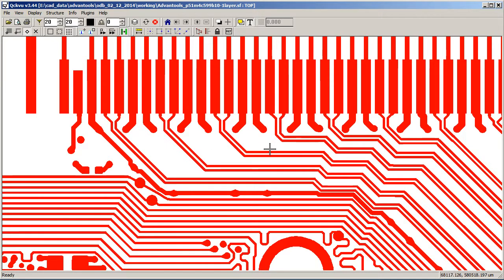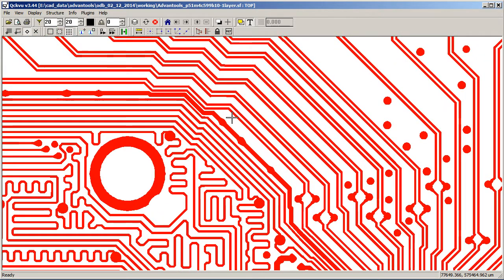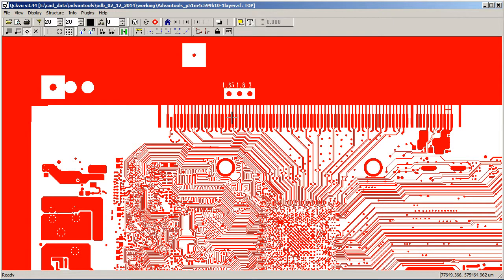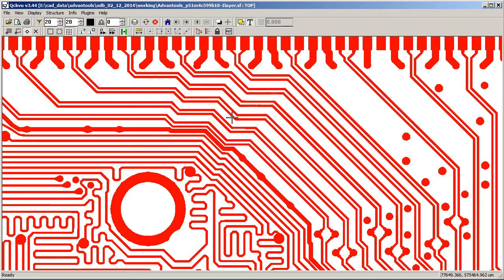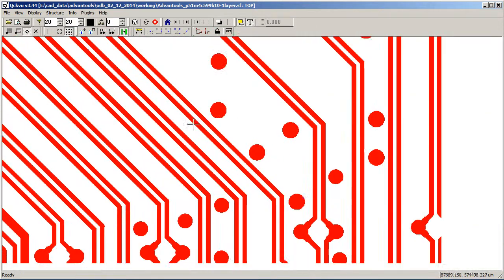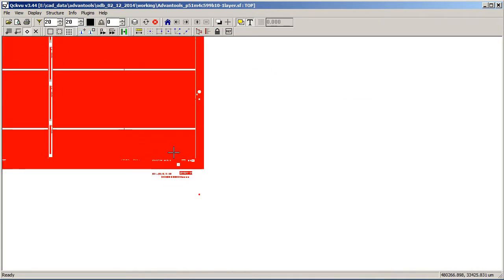If I want to pan, I just hold the middle button down and then I just drag it to where I want it to go. If I want to zoom in and zoom out, I can just roll the middle button one way to go out and the other direction to go in. So you can see that all of the manipulation is very fast. If you need to go to the other side of the drawing, you zoom out, pan over, and then roll in.